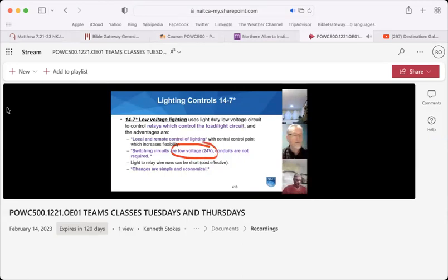And that's an advantage of using a 24-volt switching system. You can have cheap wires and multiple switches to give you all kinds of local control, remote control. So buildings wired like that were set up so that lights could be left on at the end of the day. Cleaners come in after the end of the day and they're going through the rooms.